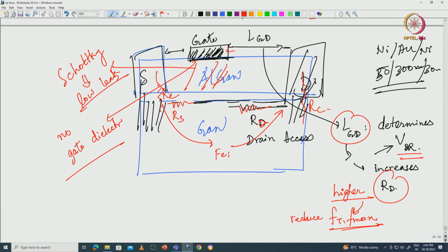Typical AlGaN/GaN HEMTs are used for power amplifiers, PA, and I told you in the last lecture that they are typically used for power amplifiers, although they are now increasingly being investigated for low noise amplifiers and switches. Commercially they are available, and even integrated TR modules are available, but still the dominant market is the power amplifier. Gallium nitride HEMTs can significantly outperform any other technology for power amplifiers.